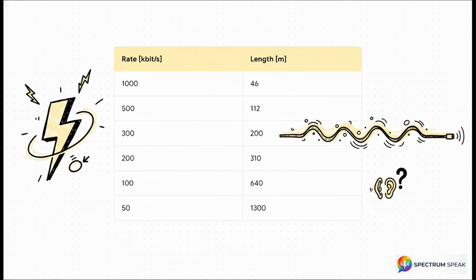When multiple nodes start talking at once, the physical voltage changes actually need time to travel down the entire length of the copper wire and bounce back so every single node can hear the megaphone. If your data rate is too fast on a cable that is too long, the bit time will end before the signal physically reaches the other side and the entire network crashes. You just can't cheat physics.